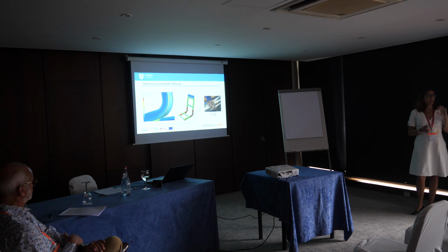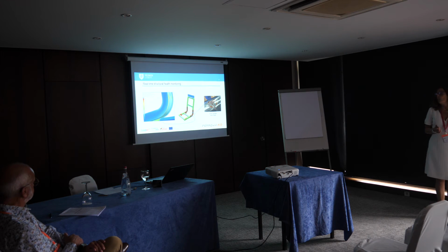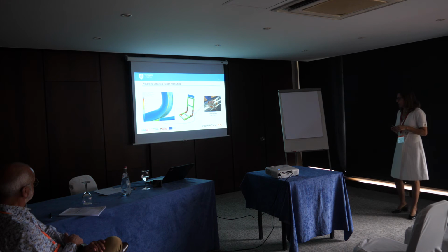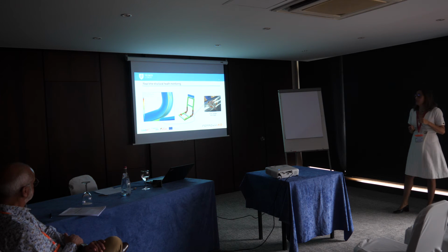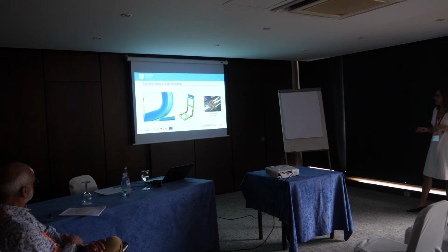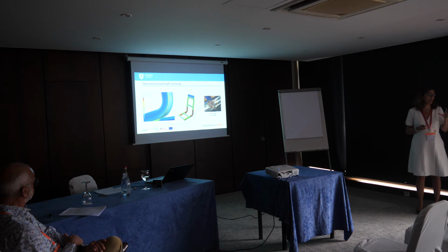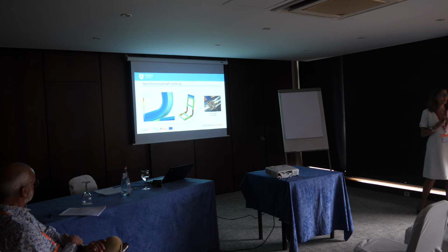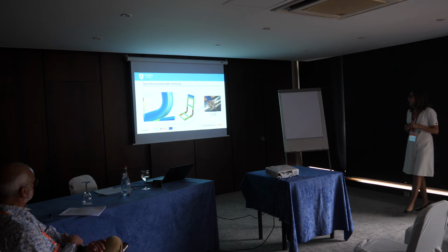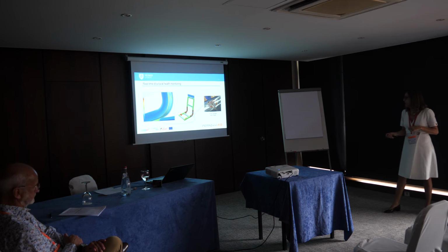The second part of the study was to define the sensors that we want to apply in the structure. We use the finite element analysis to locate the points with higher values in terms of stresses, and it was here in this location, in the reinforcement, and we decided to bond strain gauges in a full bridge in this location. At this moment, as you can imagine, we are trying to obtain the sensors, and we have a few problems with this.